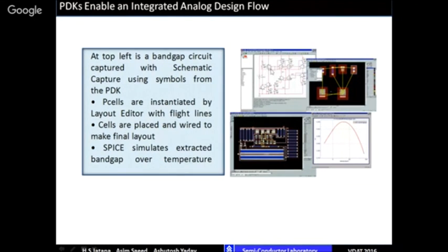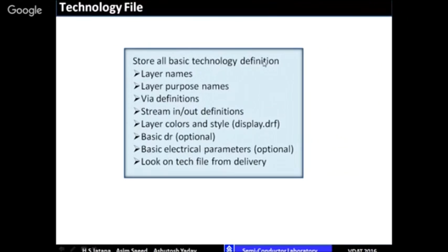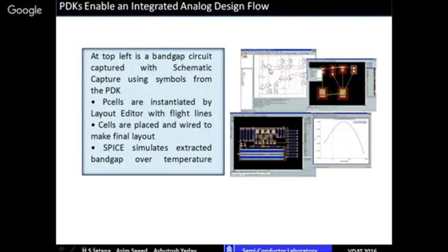So this transistor finally has to be laid out. So you call the PCell, and the PCell will lay out this particular transistor, and you call this element for PCell. For this element they will do all these layers, as shown in this figure, and it will interconnect. So you get a complete physical design of this,